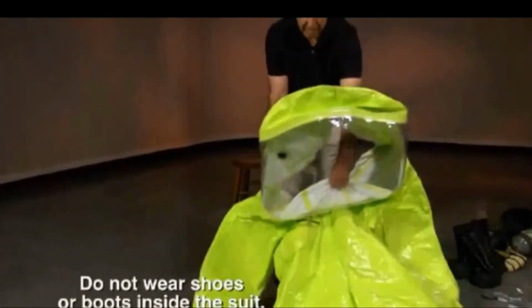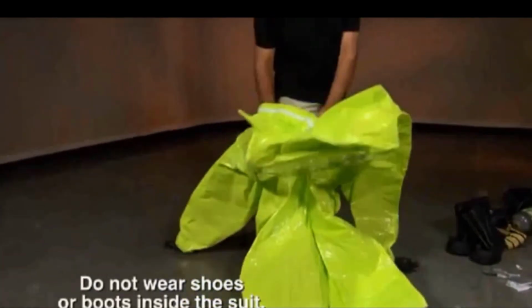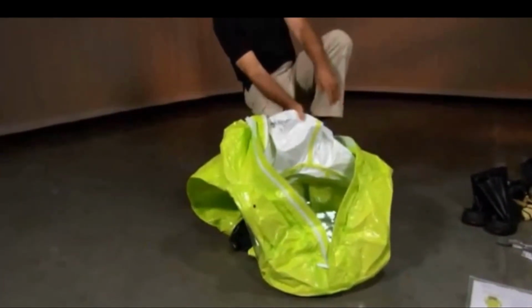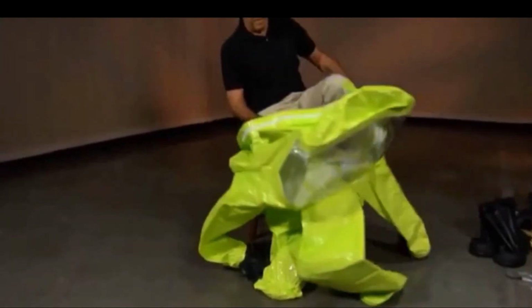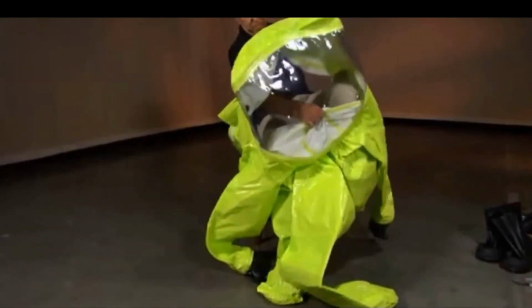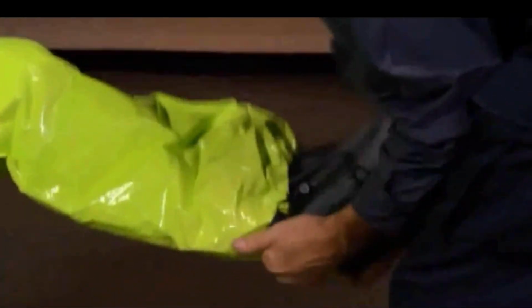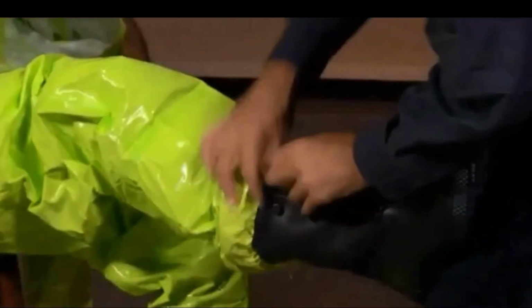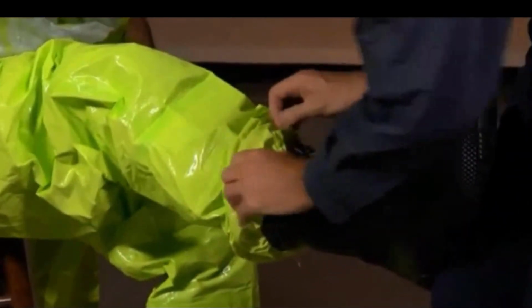Begin by inserting feet without shoes or boots into suit. It's best to have a helper assist when you don the suit. Sitting on a no-back stool or bench is recommended. Put on appropriate chemical protective boots. Leave slack in toes of sock for wearing comfort. Put on outer boot covers if required. Pull garments' boot flaps down over boots. Stand up and wiggle toes.